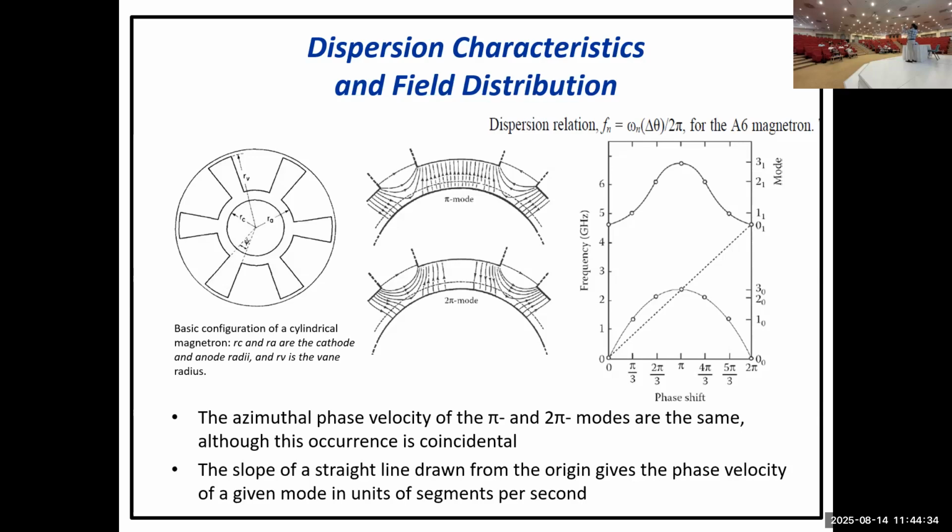I can twist it in another coordinate, but if you have this twisted in this coordinate, you're going to have a linear device like a BWO or traveling wave tube. So you can treat both problems in a parallel plate setup where one of the plates is corrugated, and this is what I'm going to show you in the afternoon. This is the first step to design your source, to get the dispersion curve and to understand it very well.